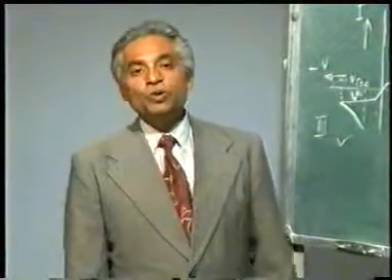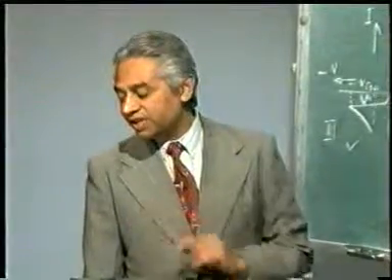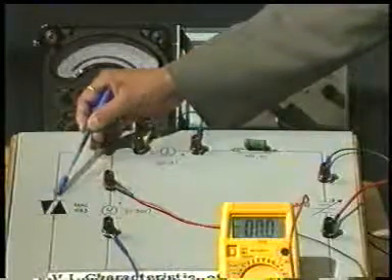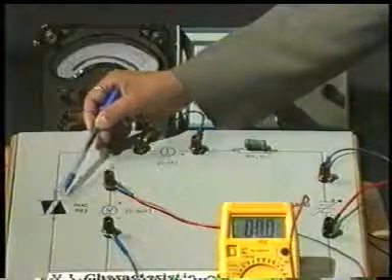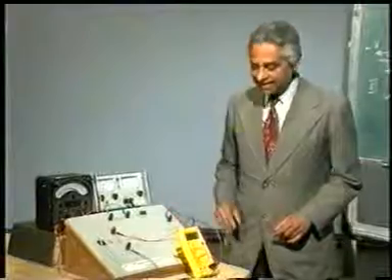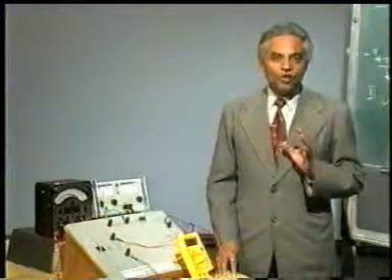One thing was very clear here. Second thing, we could know what is the value of VBO. For a particular diac, what we used here was DB3. This particular diac, what we have used here as the experimental diac, it is DB3, and for this particular diac we have verified that the VBO was around 32 volts. So these are the two very important points.